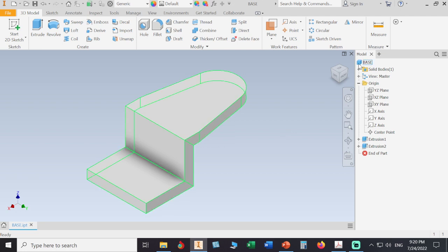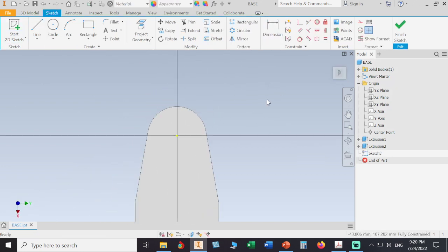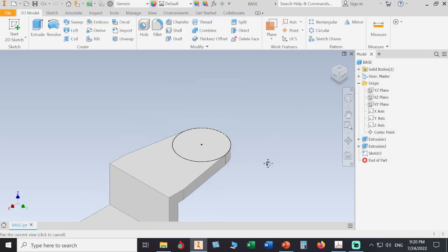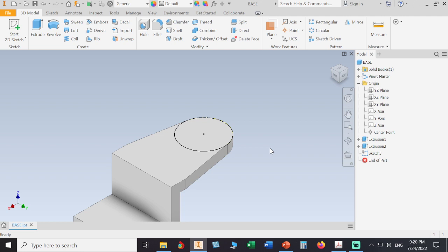The cylinder will be on this face. I'll hit this face. Sketch on this face. We have a center. That's why we start with this one, in order to put the base of my cylinder at the same point. I can give it a dimension, or I can make a tangent with this one. They are the same size. Finish. And now we have a new thing to do.